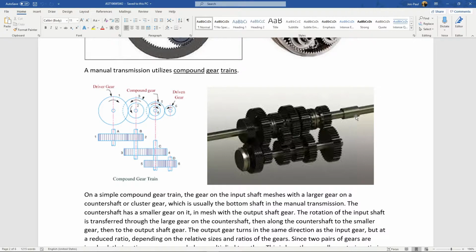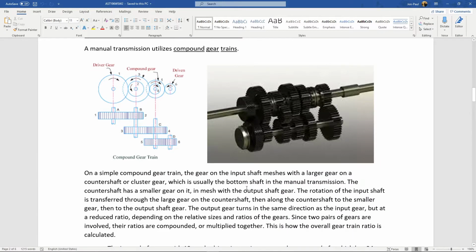So then you're going off road, so you put giant tires on it. You put some big old mud tires on it, and the diameter is now 2 inches bigger than what it was. Well, nobody told the input shaft sensor this, and so it's continuing to do its math, and it's rotating at whatever speed is supposed to be 60 miles an hour, and really you're only doing 50, or vice versa. So if you're thinking about changing the wheels and tires, just be mindful of this. There are a lot of workarounds for this where you can correct it, but just be mindful.